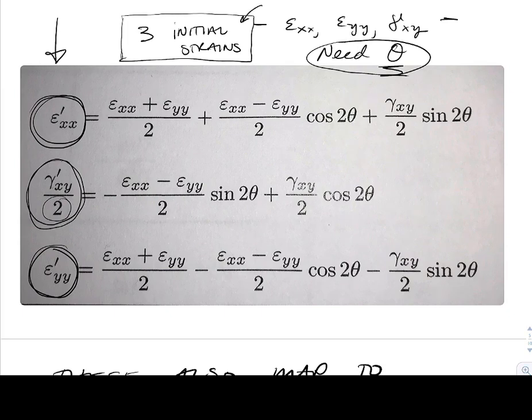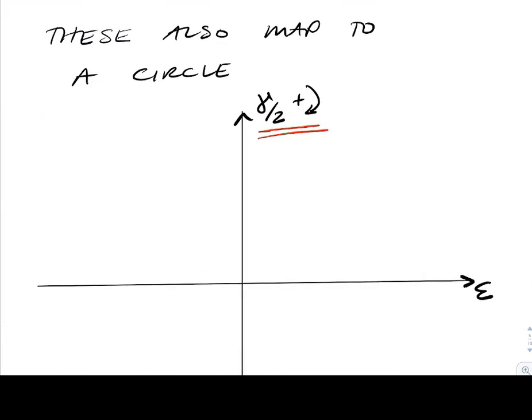And we also know the initial strains relate to the initial stresses. So those will start coming up in these problems as well. So the other thing we can leverage is Mohr circle for strain. On the horizontal axis, we're going to put normal strain. On the vertical axis, we're going to put gamma over 2, again calling clockwise positive, very similar to what we do in Mohr circle for stress.